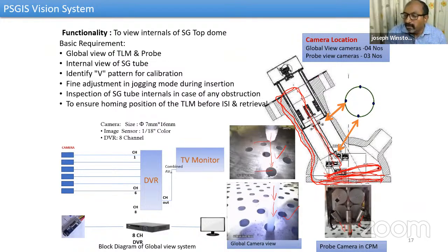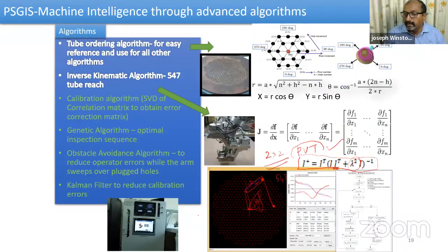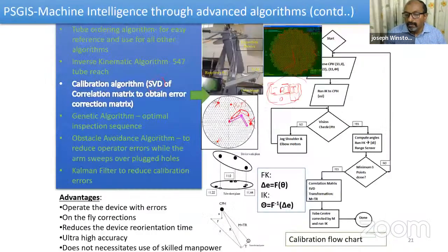So we wanted to observe these errors through the calibration algorithm. That is the reason we do the 3 point calibration and the correction based on the tilted condition. In this tilted plane, at 3 positions, we measure the errors and live with this tilted condition, but do on-the-fly correction. This tilt comes from the tolerancing and the compliance in the robotic system, which causes the robotic system to operate in a plane that is not parallel to the actual tube sheet.